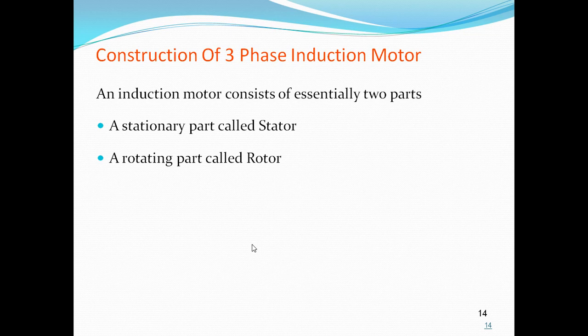It consists of a laminated cylindrical core having slots on the outer periphery and is provided with a three-phase distributed winding in the insulated rotor slots, similar to the stator winding.